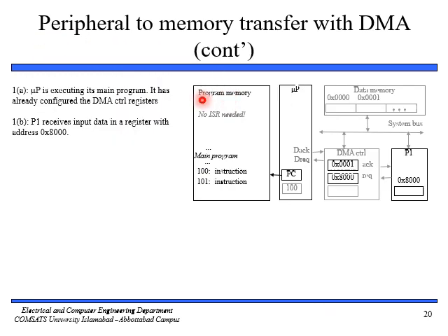So here you can see that we have program memory. We do not have any ISR, so there is no ISR, the main program is here and the processor will keep on working on this main program. We have the microprocessor with program counter and two control signals, DACK and DREQ. We have data memory as in the case of vector interrupt, exactly the way it is in the earlier slide. We have the data bus and we need to get control of this data bus.